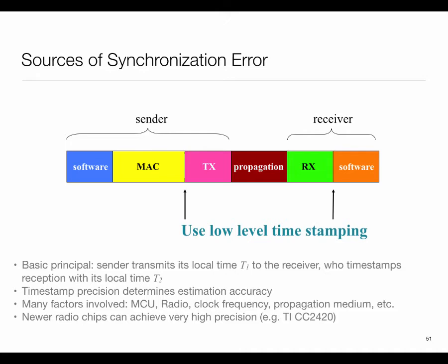Right, so it has to save the stack, right? So some delay is going to go into that. Now there are some specialized processors where they carry two register banks. So the interrupt is very rapid. As soon as they go into the interrupt, they start using the other register bank, and so they never have to save the registers. Okay, but there would still be a few clock cycle delays. Most processors don't do that. There is an explicit saving the register phase which is going to happen. Okay, so that's one issue.